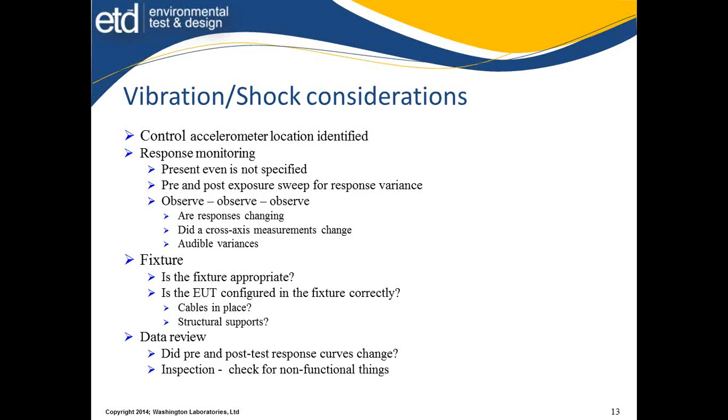Any structural supports that are in the mount should be there. They shouldn't be left hanging out if I'm going to put a mounting structure into the rack or any installation. Consider that a test article needs to be in a manner that represents what's going to happen to it. Getting pre-test data evaluations needs to consider this.